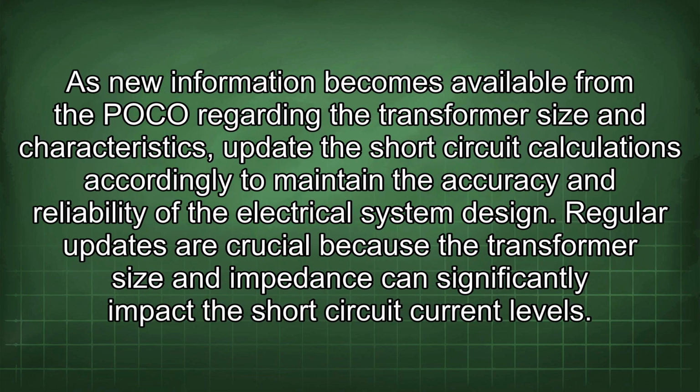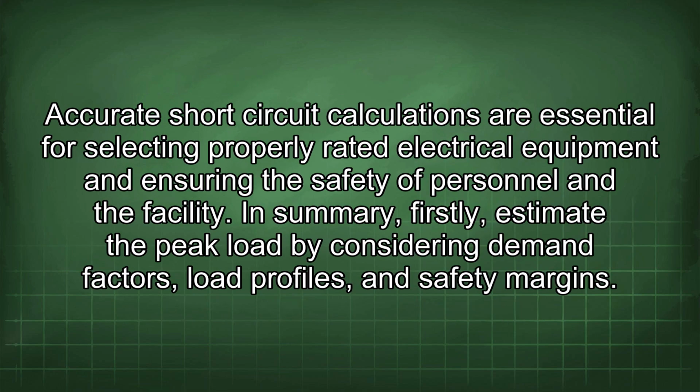As new information becomes available from the POCO regarding the transformer size and characteristics, update the short-circuit calculations accordingly to maintain the accuracy and reliability of the electrical system design. Regular updates are crucial because the transformer size and impedance can significantly impact the short-circuit current levels. Accurate short-circuit calculations are essential for selecting properly rated electrical equipment and ensuring the safety of personnel in the facility.